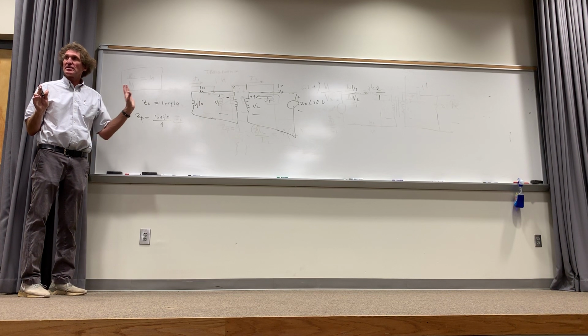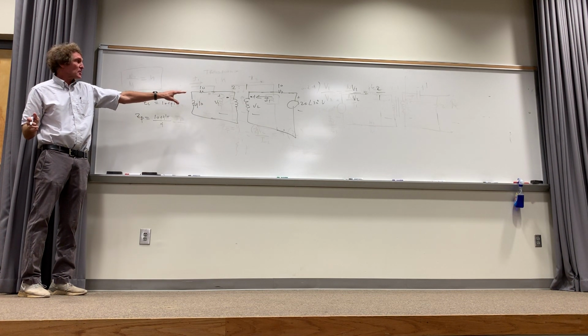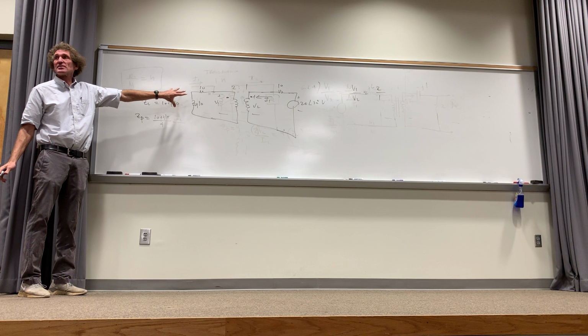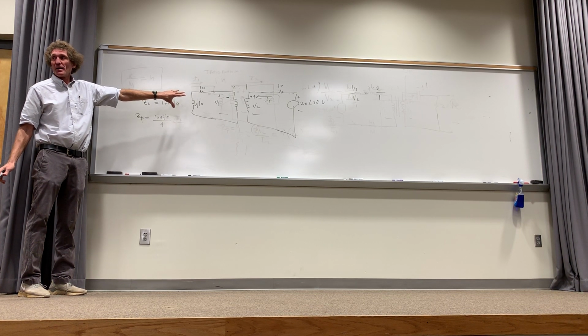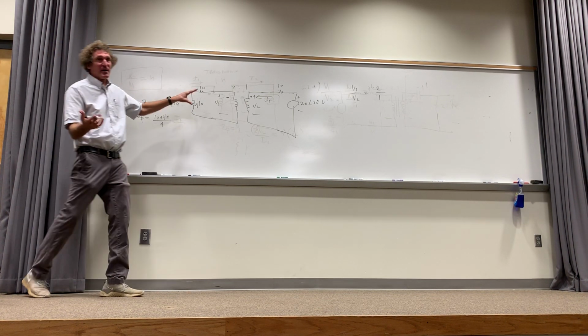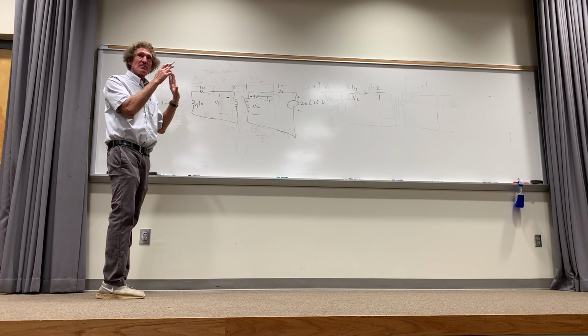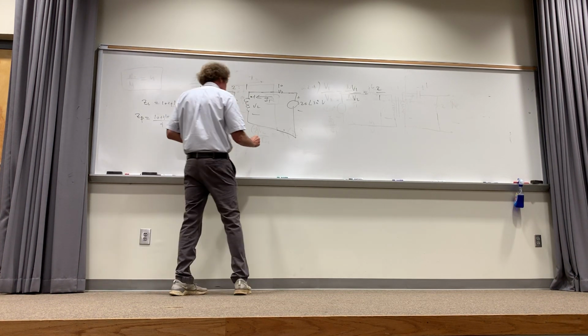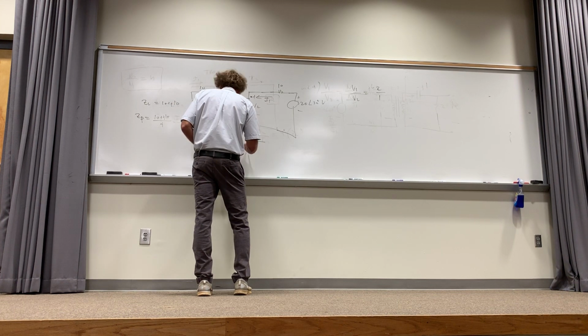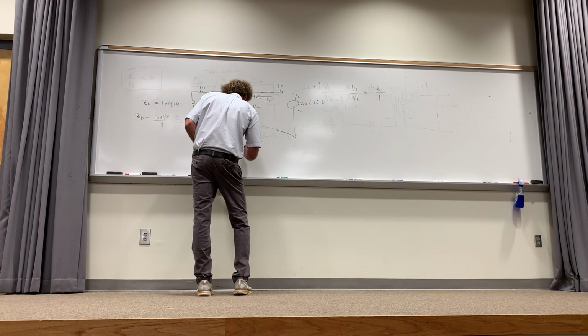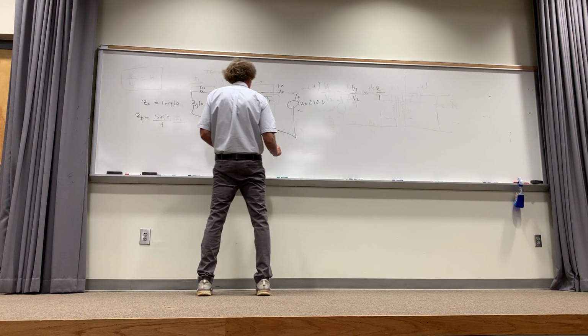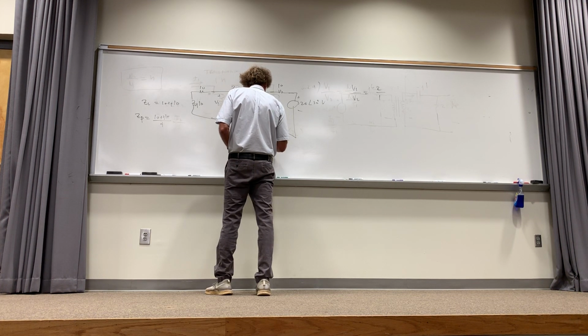I'm reflecting the impedance to the secondary, because the circuit's load is on the primary side here. It's really just turning the problem around. That's all we're doing. Does this make sense to everybody? I'm doing my best not to make it too crazy. So now what does it look like? This second coil here is going to be replaced by that. And I want to leave it as 10 plus J10 divided by 4 for a reason, so everybody sees where that comes from. And then I put on the 10 ohms here.